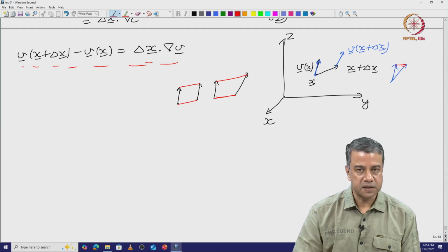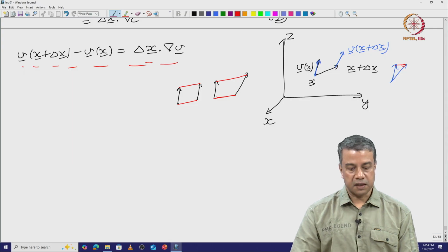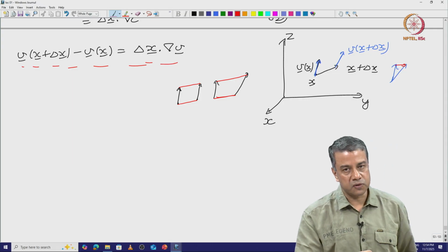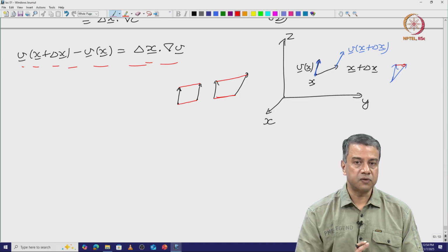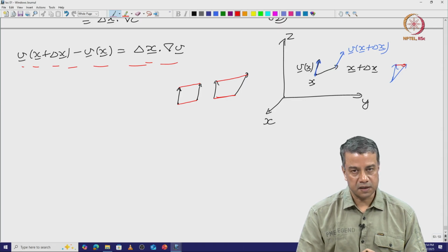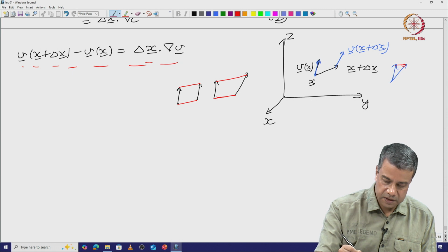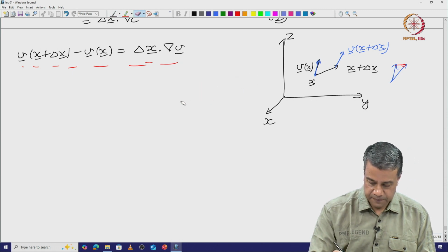It is only when there is stretching of material elements that you will generate internal stresses. Therefore, the internal stresses have to be proportional to the velocity gradient itself. They cannot be proportional to the absolute value of the velocity, because that is just a constant translation and there is no stretching or bending. So, therefore, these have to be proportional to the gradient of the velocity.